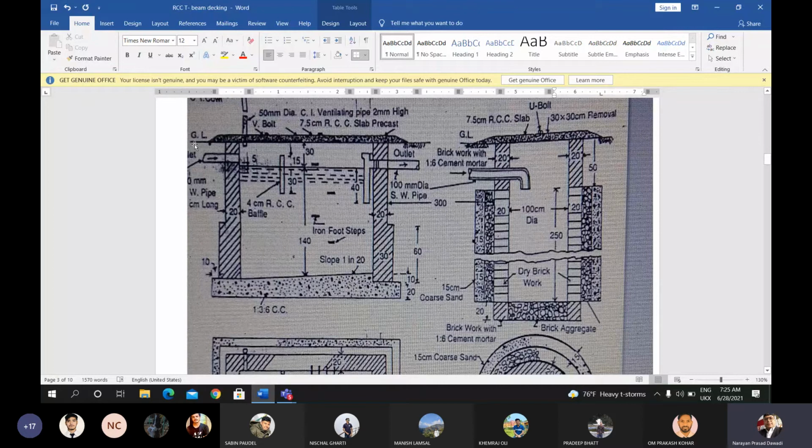So, we have to excavate all the soil from below the ground level up to the bottom of the cement concrete or PCC. That soil is excavated and dug out from the ground, and the trench is prepared.